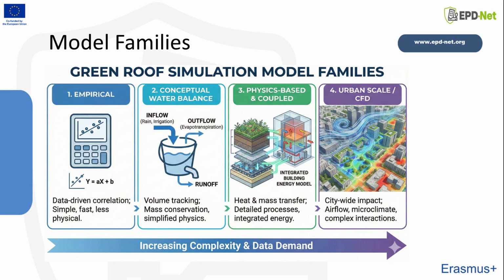Coupled building energy approaches integrate a green roof module into whole building simulation so that roof behavior affects indoor loads. At the urban scale, microclimate models and CFD resolve airflow and radiation interactions, but their input requirements and computational cost can be substantial. Model selection should match the decision, the data you have, and the level of uncertainty you can tolerate.